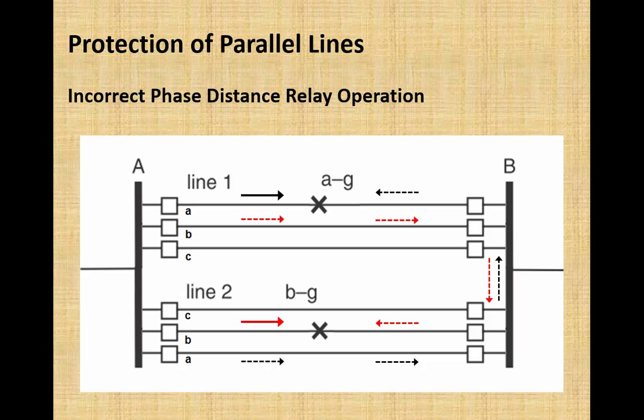But if we are practicing single pole operation of the circuit breaker, that is problematic, because in case of a line to ground fault, tripping of only the faulty phase is required, followed by immediate reclosing. But due to this simultaneous existence of fault current, this fault would now be considered a line to line fault, so all three phases will be tripped.